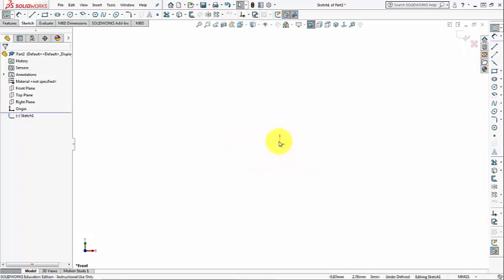First, I'm going to take care about the shape, roughly the shape. And then I will start my sketch at the origin point. So this is rule number 2. I have to relate my sketch to the origin point. And also, I'm going to get the sketch fully defined by adding some sketch relations or constraints, and then dimensions.